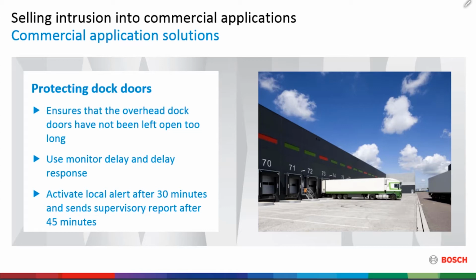Well, we can use monitor delay and delay response to monitor that door as well, but we would have a different timer. Obviously, for a door a person's going to go through, a minute is enough. But I need a half an hour to empty that truck, so I'm going to set that timer for 30 minutes. So after 30 minutes, if that door is still open, the keypad is going to start beeping at you.